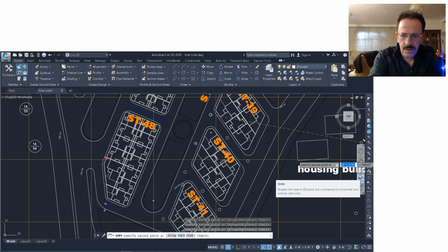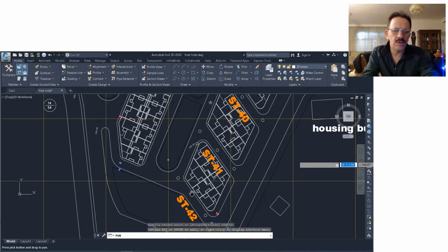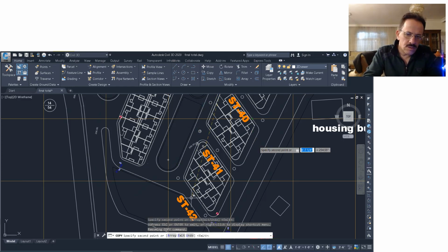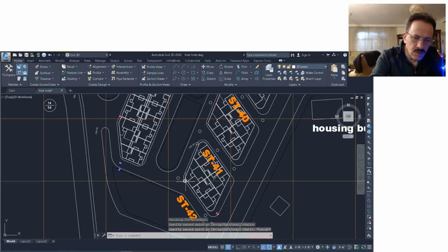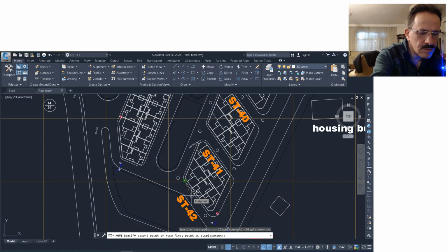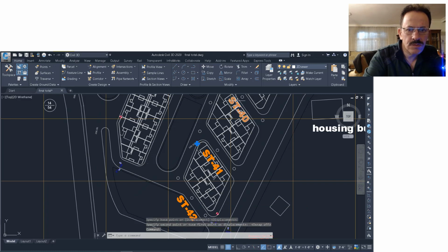You have to be precise in the location, because the location is very important. And during the work with AutoCAD, I prefer you turn off the snap, and this is F3, so it can work easier. Also we have this one, move from here to there.